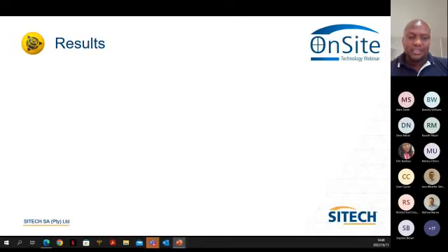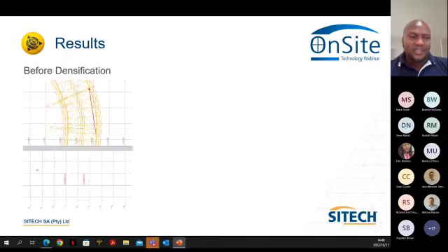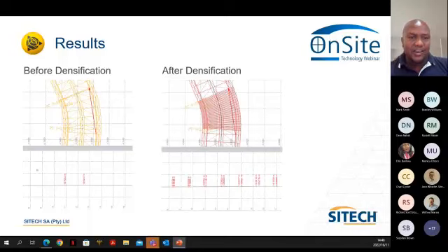So in terms of results that we did in TBC, there's an example of a surface before it's densified. In this case, I presume the road was done maybe every 5 meters. And along each section, after you densify your road, only the sections where your road is a curve, where additional cross sections or triangles are required.